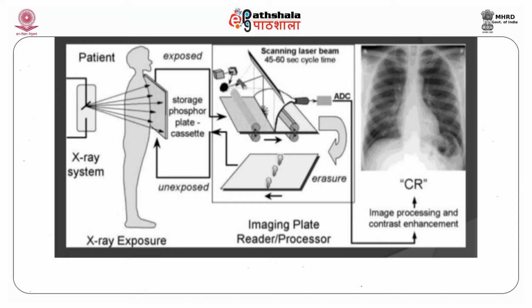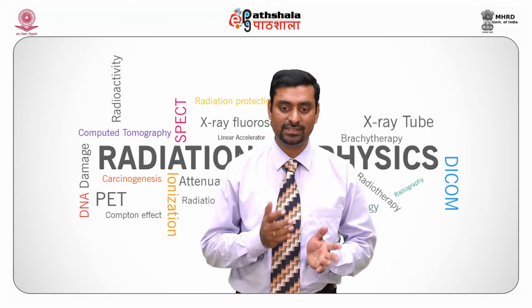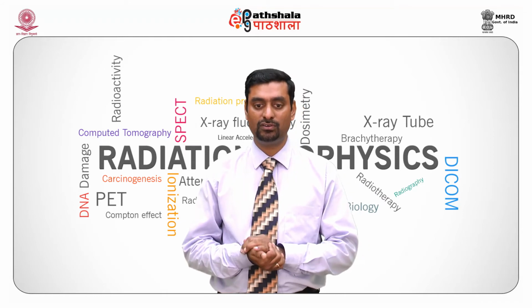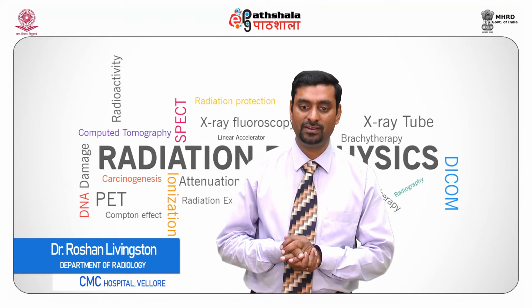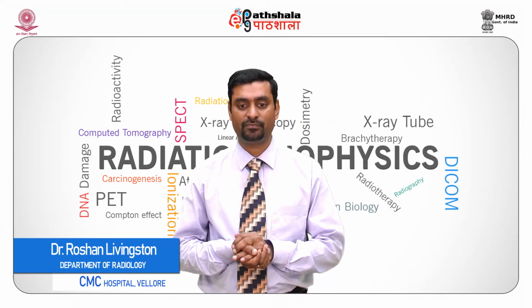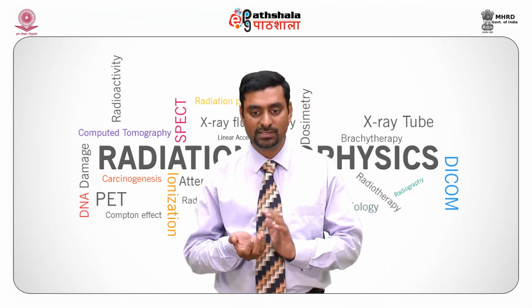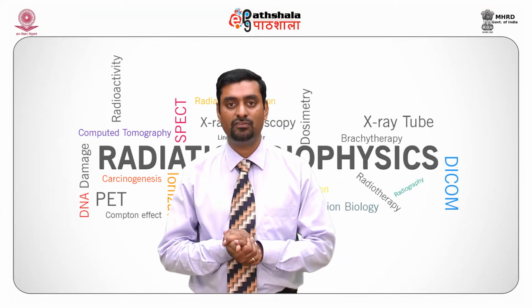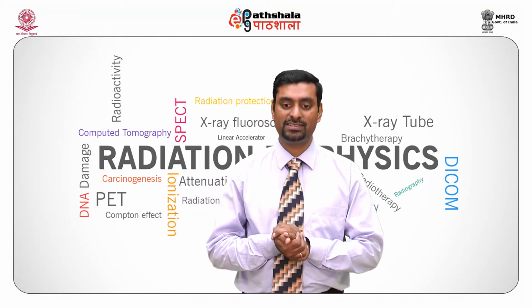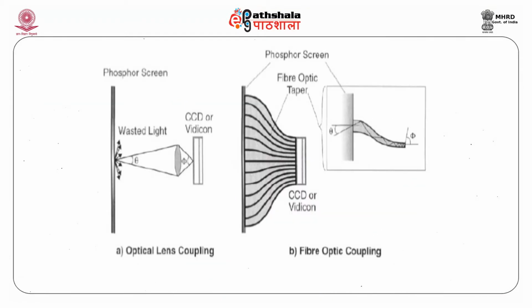The general principle is X-ray photons, which are produced from an X-ray machine, and a scintillation material. The use of the scintillation material is that when X-rays fall on it, it produces light. Cesium iodide or gadolinium oxysulfide are used as scintillation materials. And then we take it through the optics. In some cases, we reduce the size of the image. And finally, the image falls onto a charge coupled device camera, which converts the light into an electrical image.